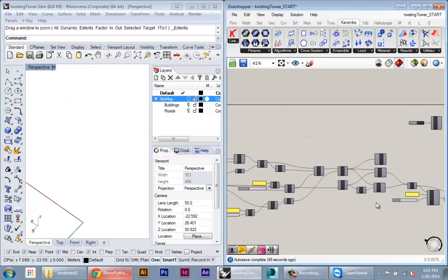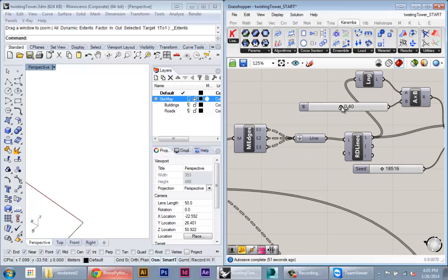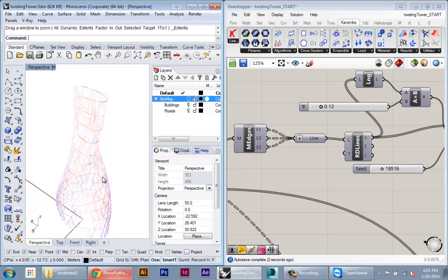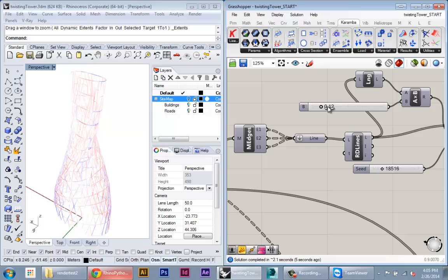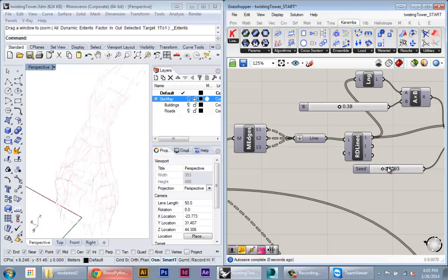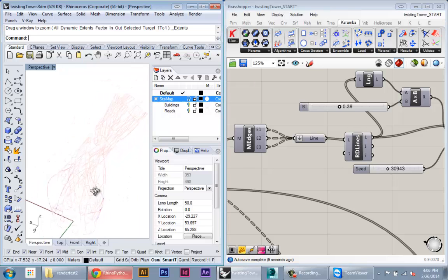Okay. And then we can also try to see what happens if we have more or less reduction in our elements. So here we're going more towards a full mesh, we have better performance. And going more towards a reduced mesh, we have worse and worse performance. So you can see how real time this feedback is, and this is really useful because you can get pretty much instantaneous structural feedback once you set this up that you can use to make decisions in your design.